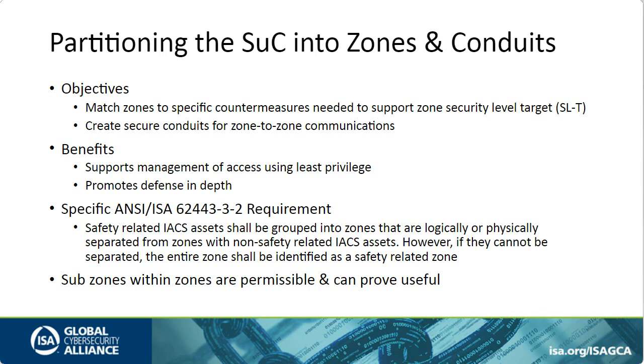Also want to note that subzones within zones are permissive and can be very useful. So, for instance, if you have a safety zone with a safety instrumented system, a safety instrumented system is comprised of sensors, logic solvers, and final elements, and workstations to do your configuration of the controllers.